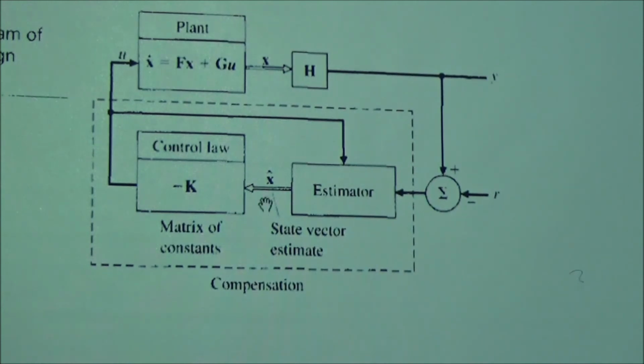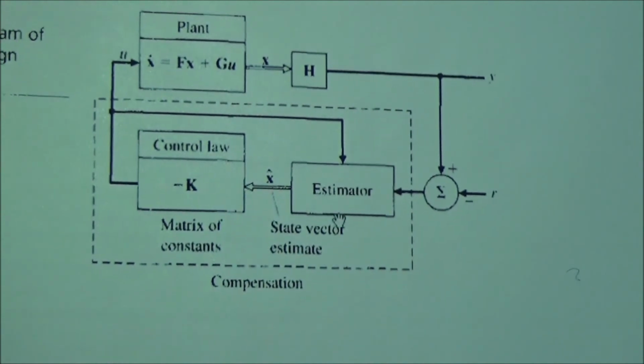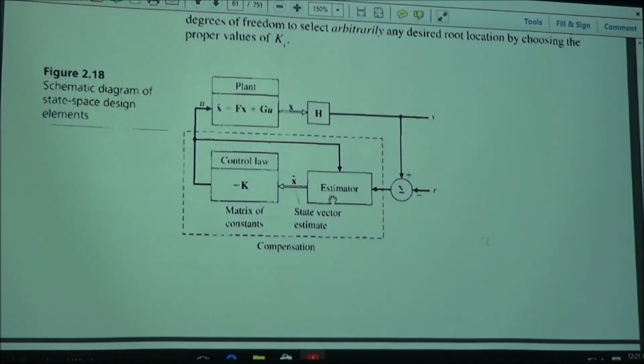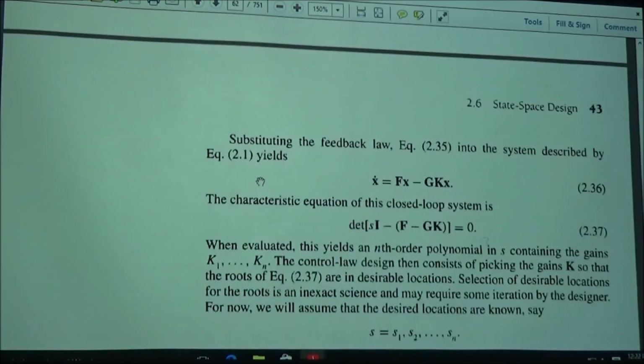So if you have a state feedback, you need to find an estimator, additional hardware, using the input and the error of the output, and combine them to give you the estimated state. And that is going to give you some kind of observer. We sometimes call it Luenberger observer, after Professor Luenberger at Stanford who came up with that in the 60s. And then pole placement is going to be done here.